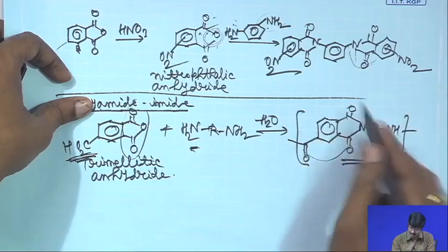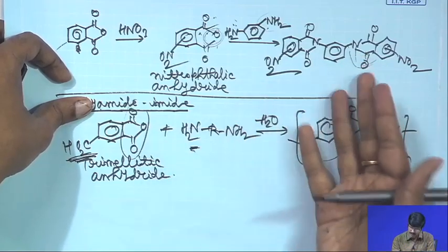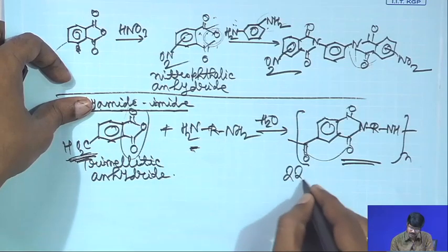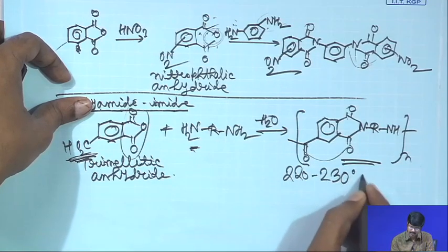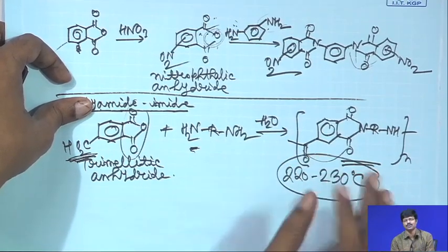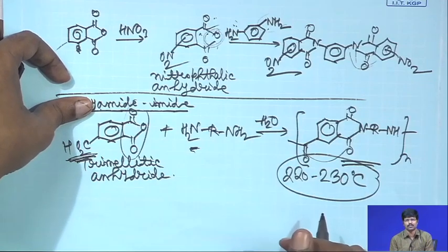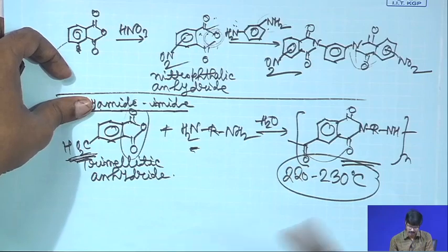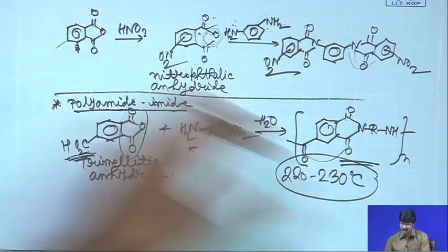This also will have high strength, high stiffness, and these are amorphous polymers, and the continuous use temperature is around 220 to 230 degrees Celsius. So, these do not fare too badly with respect to your typical, conventional polyimides, but some of these materials are easier to handle.